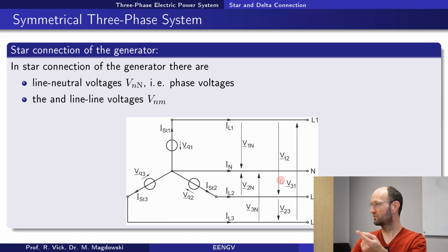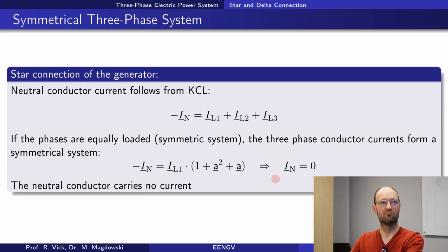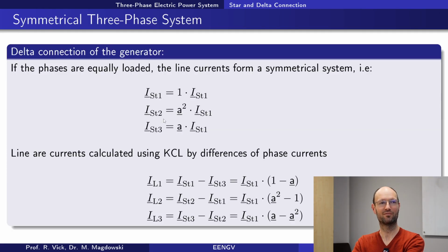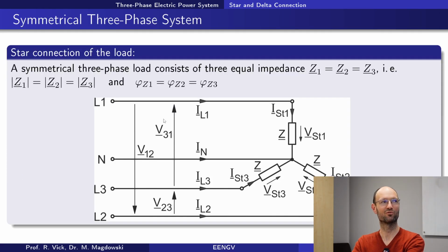The line voltage is square root of 3 times larger. And so here voltage and voltage is equal, but current is not equal. The line current is square root of 3 times larger. This is what I would remember. This is what I can remember, and I don't have that big a brain to remember stuff. So this is what I can do. Probably you can also do it.